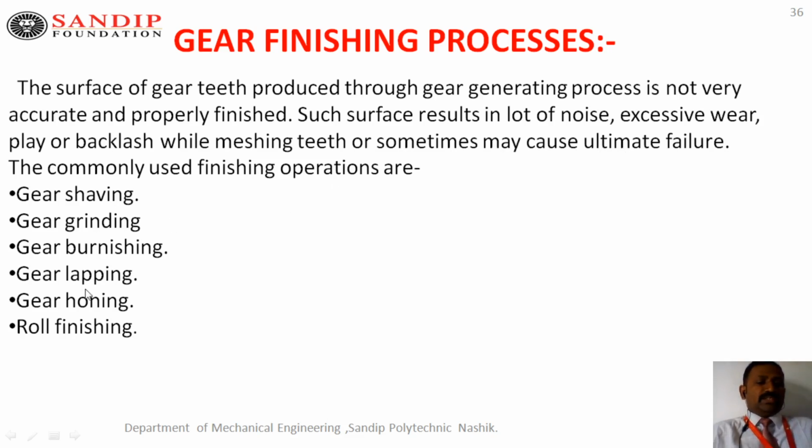As finishing methods, they are as follows: gear shaving, gear grinding, gear burnishing, gear lapping, gear honing, roll finishing. So let's see them one by one. These are the gear finishing processes. We start with gear shaving.